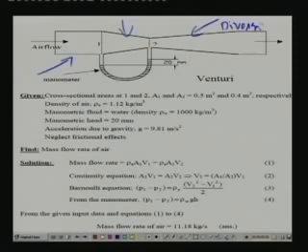portion, this is the converging, and where the diverging and converging portions meet, we call that portion the throat of the venturi. And here, the inlet to the converging portion is 0.1 and the throat portion is 0.2. And the venturi has a manometer here, and one end of the manometer is connected to the inlet to the converging section, that means 0.1, and the other end of the manometer is connected to the throat portion, that means 0.2, and this manometer is filled with some manometric liquid.